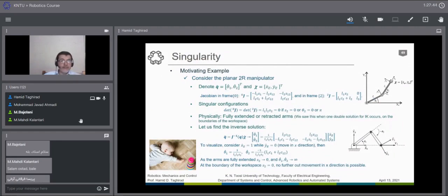Say, for example, we have theta 2 at 1 degree or 2 degrees. Then sine theta 2 is too small, so theta 1 dot is too high. So we have a limitation from the actuator used. Will this limitation reconfigure the workspace of our robot?